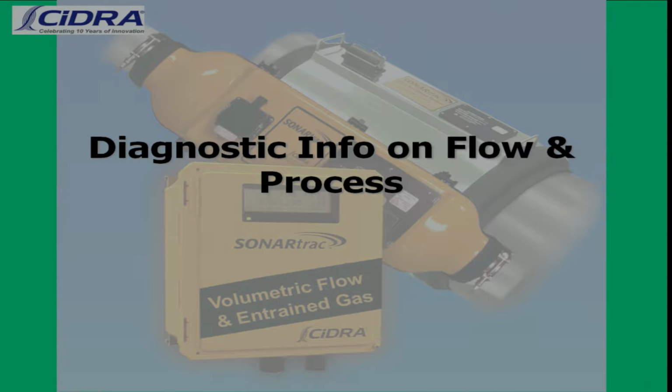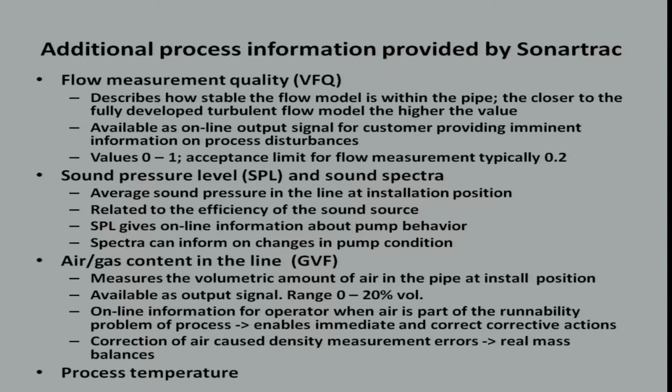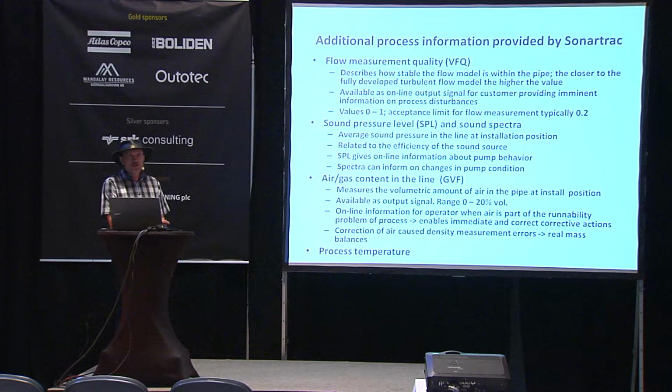How do we get this diagnostic info on the flow? We have 4 different parameters coming. Flow measurement quality describes directly what the flow model is there, how close and how stable it is. Sound pressure level and sound spectra tell you how your pumping is behaving. Is it stable, or are there changes compared to earlier statuses? Then the gas content measurement, the only technology to measure the volume of gas in the pipe. And process temperature is also available from our technology.